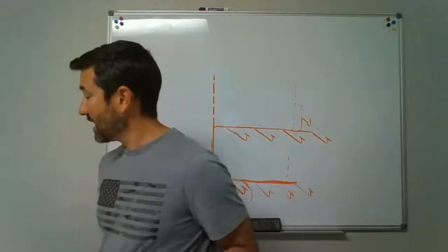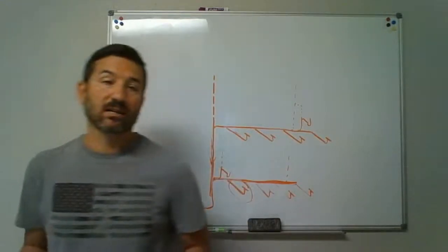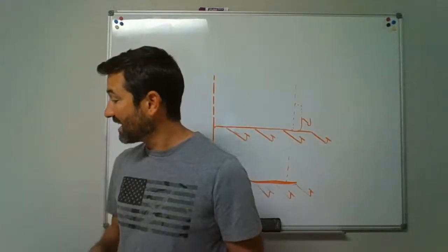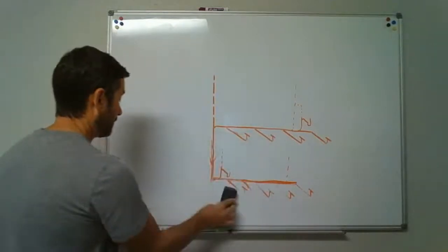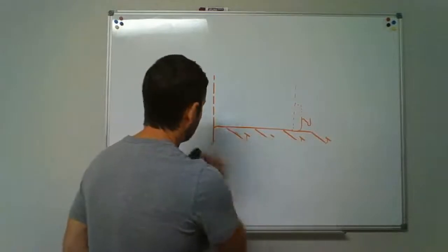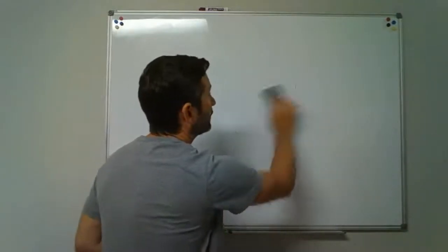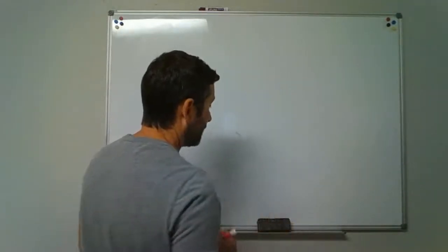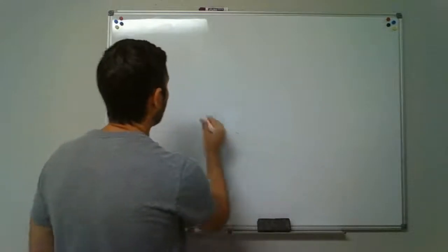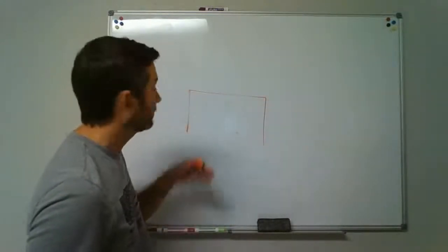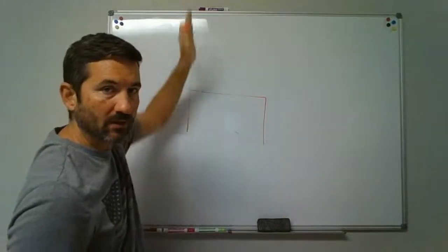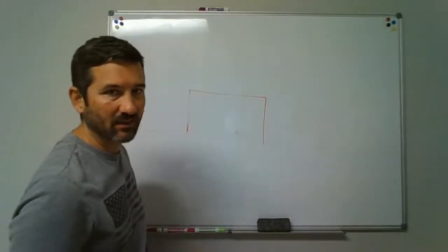Basically what this is, and I don't see much of this being done anymore, especially since we're about to go over to 918 and talk about air admittance valves. If you just really have someone that is opposed to an air admittance valve, okay, we've got an island sink. There's the island. There's no wall going up. How am I going to get a vent going up out of this island and vent for this sink?